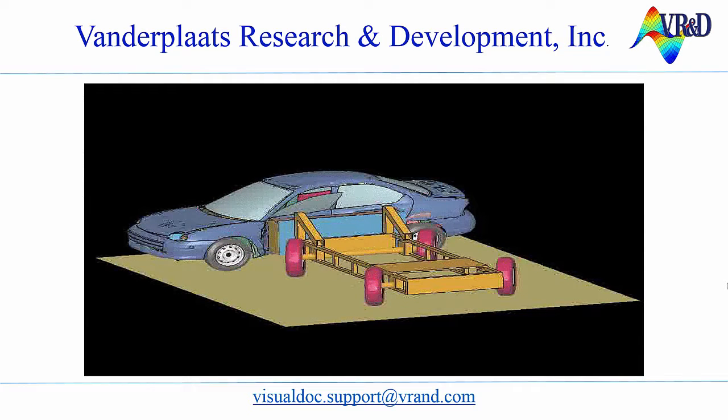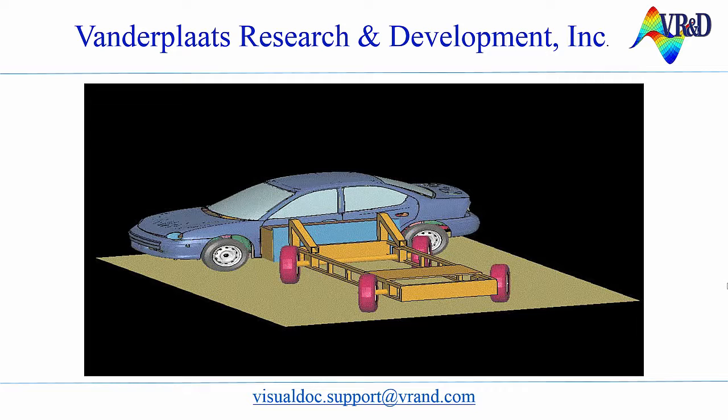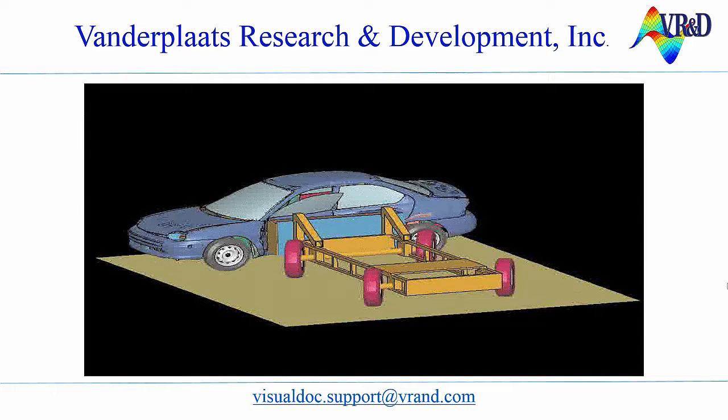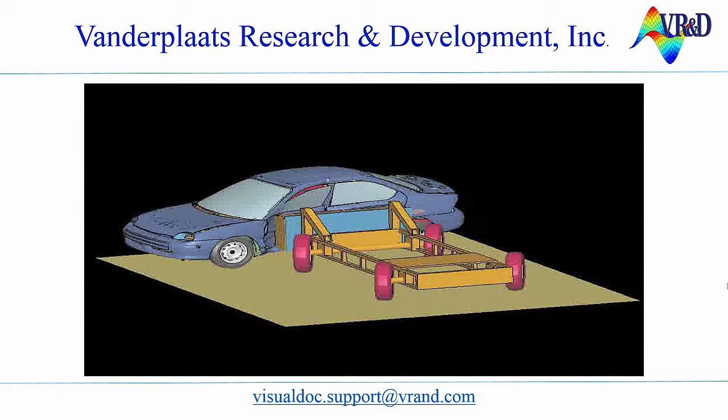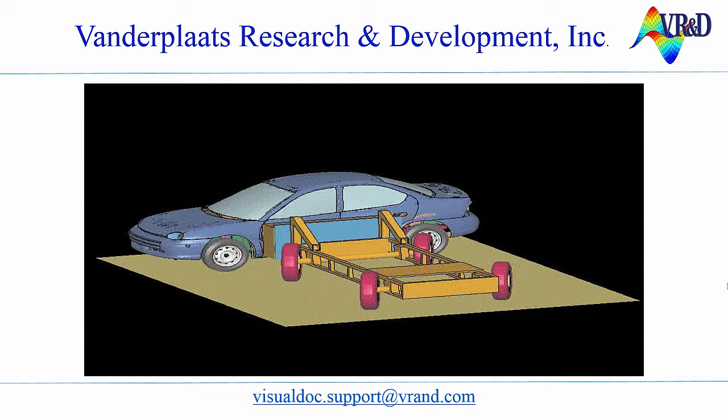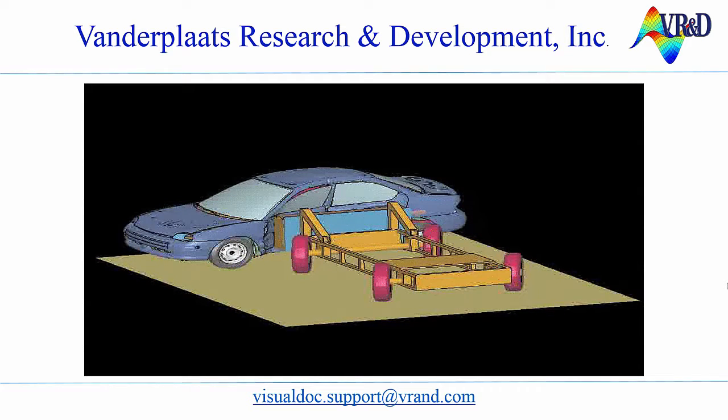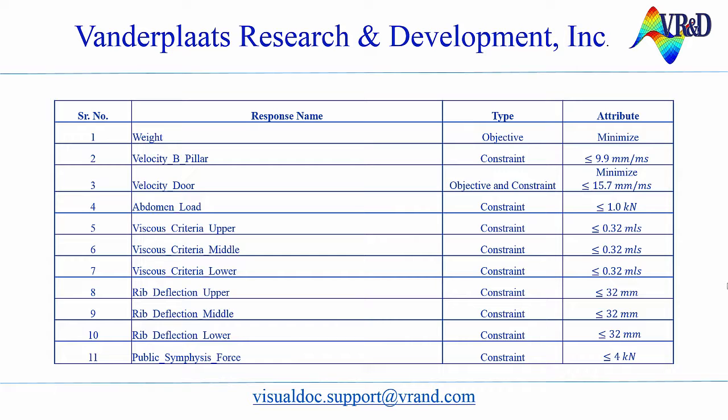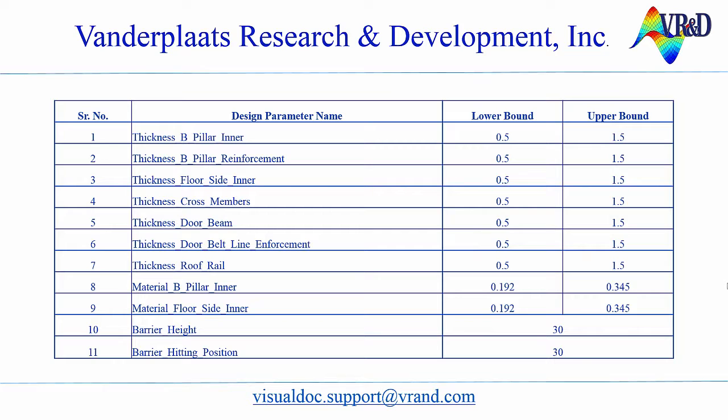The vehicle side impact model used is an approximation model generated using response surface after performing LS-DYNA simulations. The vehicle is designed to be simultaneously light and safe. Thus, the design objectives for this problem are the weight of the door panel and the velocity of the door upon side impact. These two objectives are conflicting because if the door panel is light, it may have a higher tendency to deform and impact the occupants with a higher velocity.